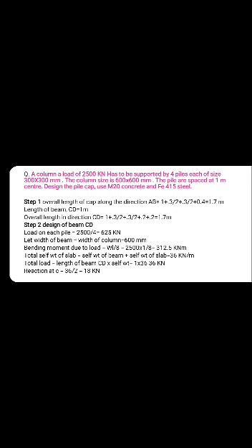Next problem. A load carrying column carrying a load of 2500 kilonewton has to support 4 piles each of size 300 by 300 mm. The column size is 600 by 600 mm. The piles are spaced at 1 meter center. Design the pile cap using M20 concrete and Fe415 steel.